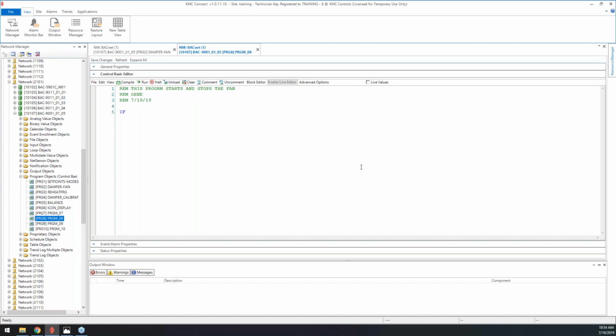So we're going to use BV5. BV5 is our occupied status. Okay, so if we're occupied, then we're going to start BO1, which is the fan.